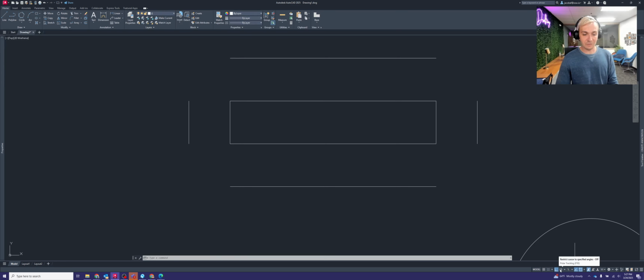To the right of that, you also have what's called polar tracking. I'm going to turn that on real quick. Polar tracking is pretty useful. So let's say you wanted to draw a line at 45 degrees, but not 90. Well, this allows you to snap your cursor to 45-degree increments as well as the 90-degree increments too. So you can see what's happening as I'm rotating around. My cursor is snapping to those 45-degree increments there. You can also set it to other angles if you'd like, but that's the default. So kind of useful if you like using that.